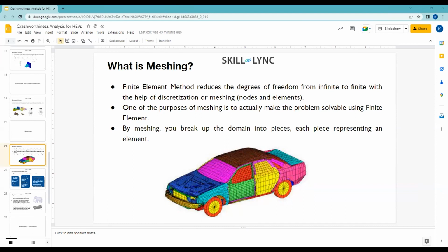Now try to analyze this with the help of 2D. These things are becoming complex even for 1D. If you go with 2D and 3D in any traditional finite element book, you will understand that this stiffness matrix is for one element. If you are studying any car body or BIW, there are n components, and within those, if there are 40 or 50 elements, there will be a very huge matrix. So that matrix calculation is hard, and linearity and non-linearity hamper your study in stiffness. I tried to explain that with the help of the 1D beam.